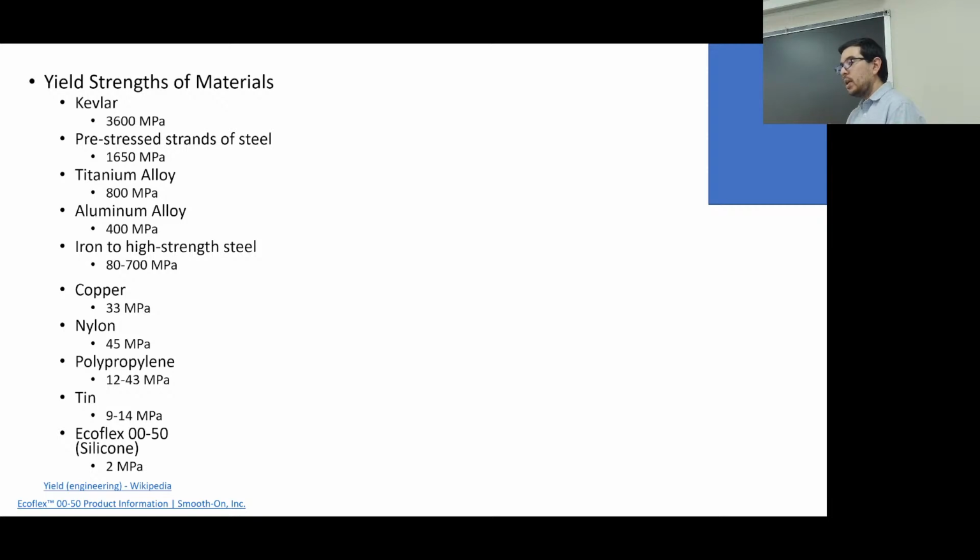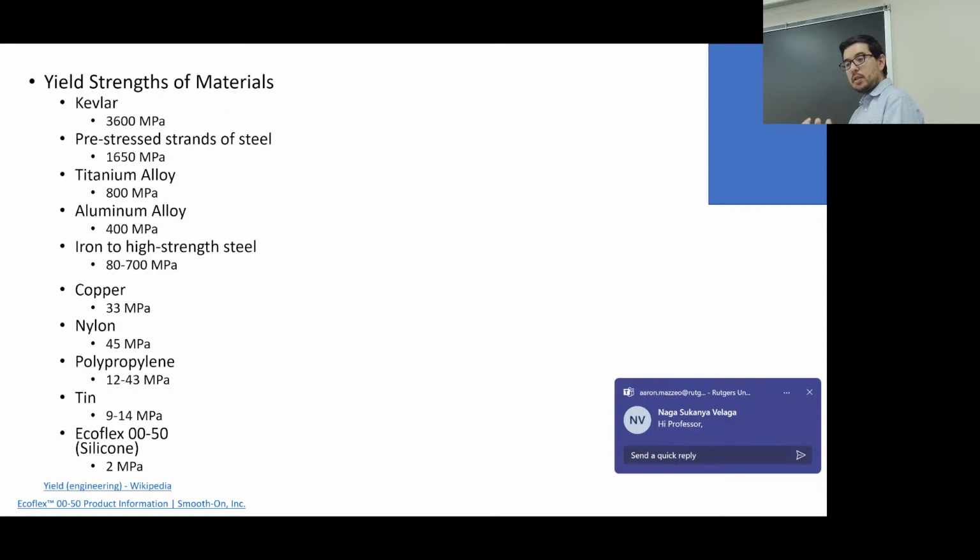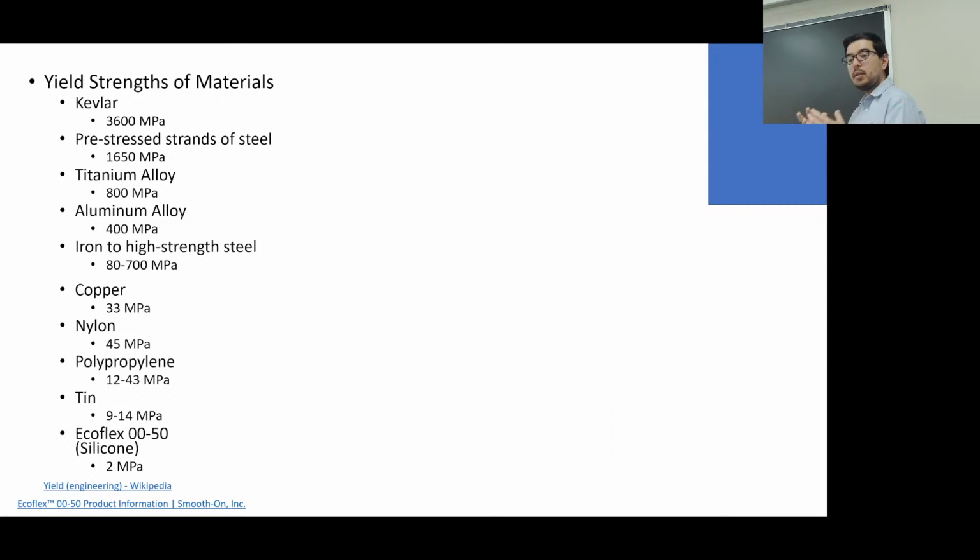Another way is what's called quenching. So you take the material, like steel, you heat it up quite a bit, and then you have a bucket of water, and you take that very hot material out of the furnace and put it in the bucket, and that quenching behavior causes that material, which is cooled very quickly, to harden or to have a higher strength.